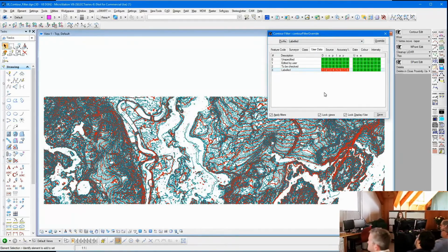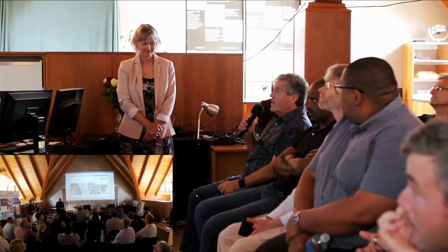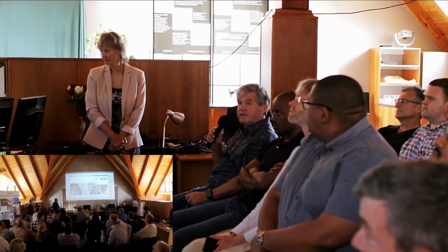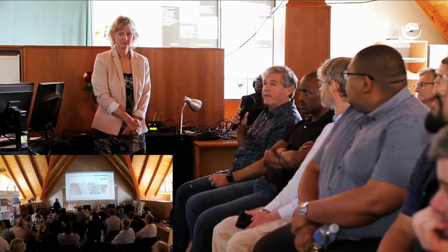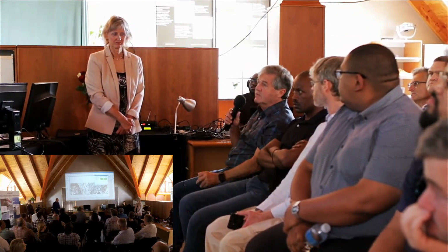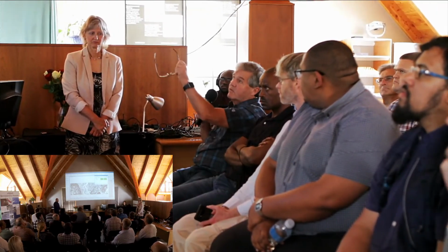Okay, so you can pre-set up these things so you don't forget. I don't see a filter from the source of the survey. Very often you want to isolate your Class A survey from the rest. For instance, you've got a structure that you've scanned and you want to filter only the information for the bridge or a building or a culvert. Can you extract that through the filter?